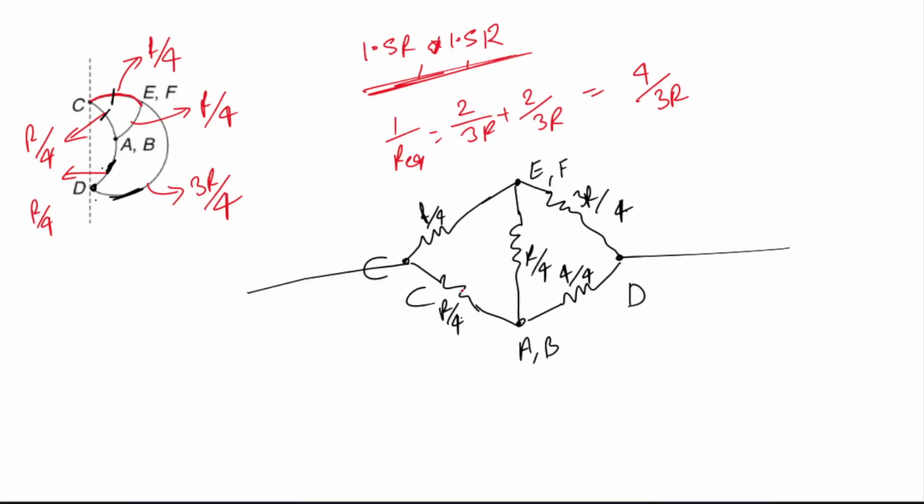So here I will reduce this circuit like this. I'm going to do this, reducing it here like this. Now look, how much will this part be? Here, for this triangle, the star I am taking has R/4, R/4, R/4; all three resistances R1, R2, R3 are the same, right? So the calculation is going to be quite easy here. If you want to write the value of this part, you will do R/4 into R/4 divided by the sum of three resistances, which is 3R/4. So this will be equal to R/12.